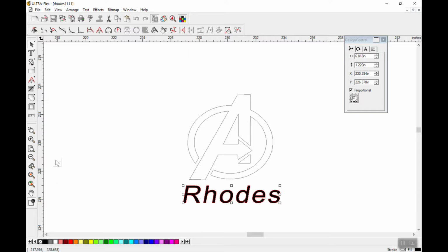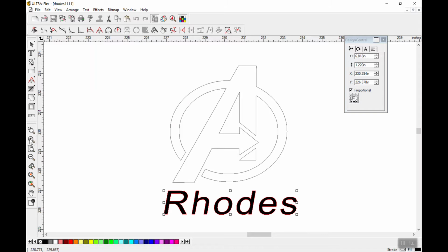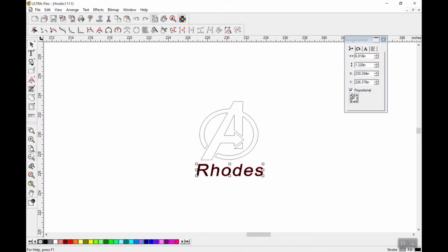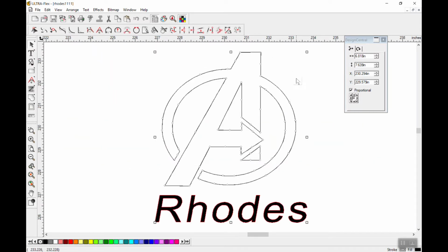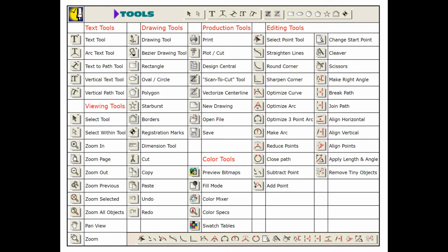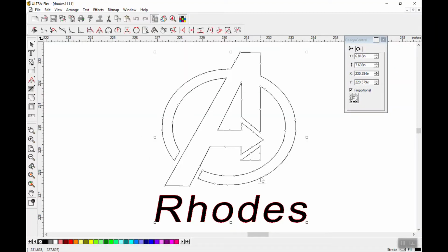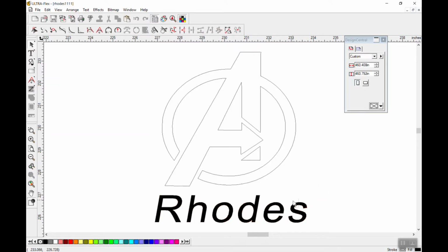The other toolbar you'll see a lot of is this right here. This deals all with your zooming. We have a zoom box that will just zoom into whatever's there. Your plus and minus will zoom in and out. And then my favorite, the zoom to selected. It'll zoom to whatever is selected completely. This right here pretty much covers most of the things that you'll use in this class. Anything more specific, feel free to come talk to me about and I'll give you a better answer.